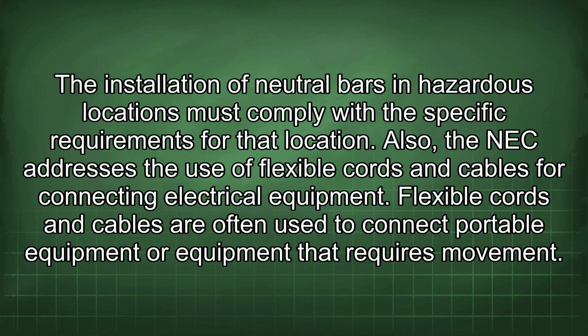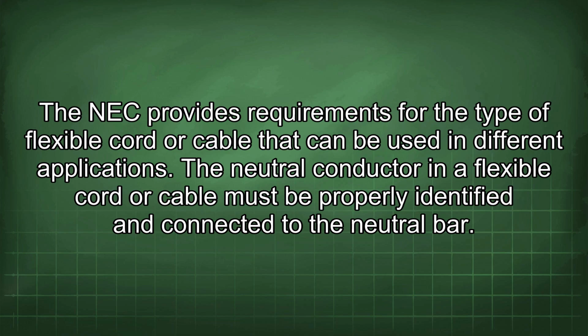Also, the NEC addresses the use of flexible cords and cables for connecting electrical equipment. Flexible cords and cables are often used to connect portable equipment or equipment that requires movement. The NEC provides requirements for the type of flexible cord or cable that can be used in different applications. The neutral conductor in a flexible cord or cable must be properly identified and connected to the neutral bar.